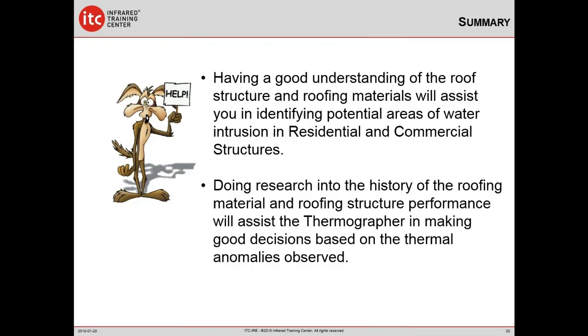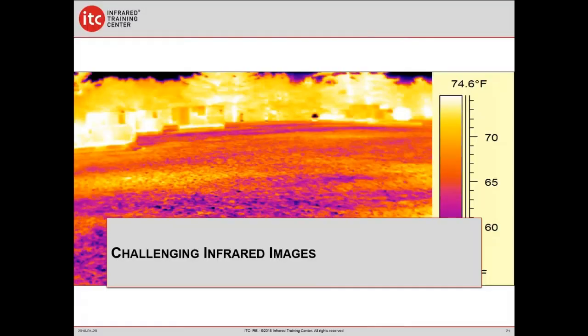I've always said roofing thermography is more challenging than a lot of other applications because, of course, there can't be any moisture on the roof. Doing it in the morning, there could be condensation in the roof. Condensation warms the substrate, and then it cools and it makes it difficult to see any moisture underneath. So all these conditions can be very challenging. So finding that perfect day is not as easy as you may think.